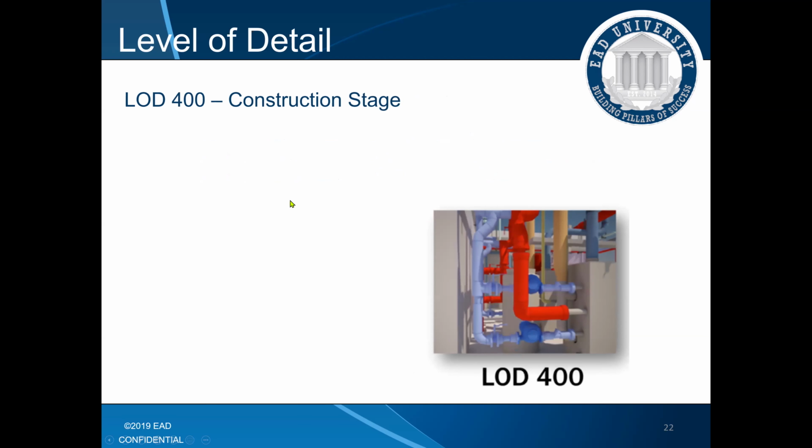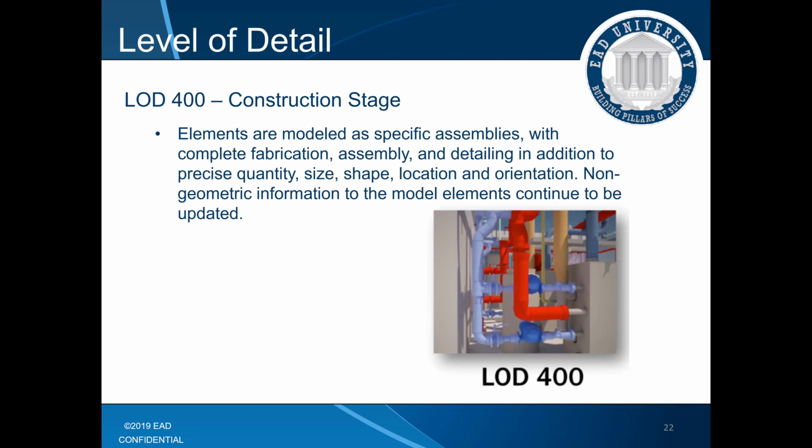LOD 400, construction stage. Elements are modeled with specific assemblies with complete fabrication, assembly, and detailing in addition to precise quantities, size, shapes, location, and orientation. Non-geometric information and model elements continue to be updated.